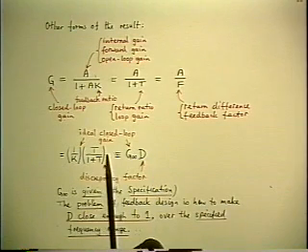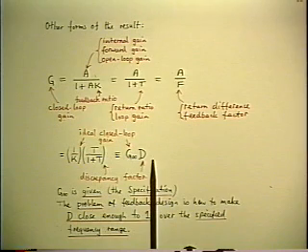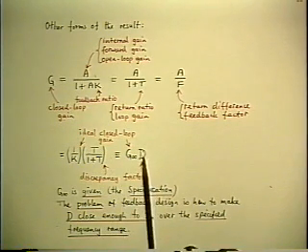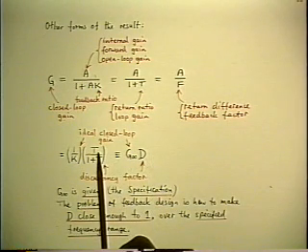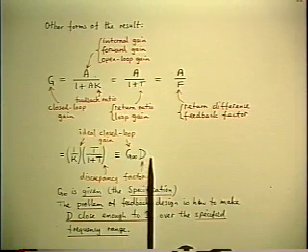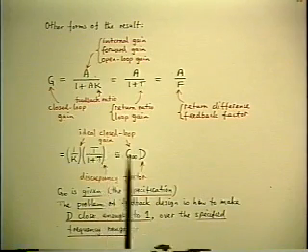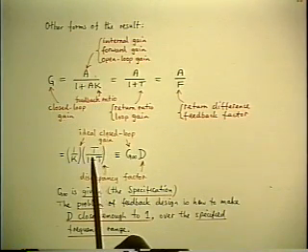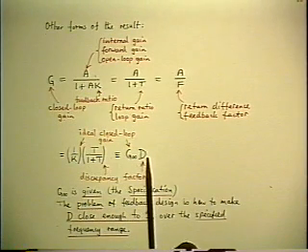The only hard part is making T big over a wide enough frequency range. As I mentioned in the introduction, you're certain to have a problem at the high frequency end because T will always go to 0. You may have the same problem at the low frequency end because if the amplifier is AC coupled, then T is going to go to 0 at 0 frequency as well.